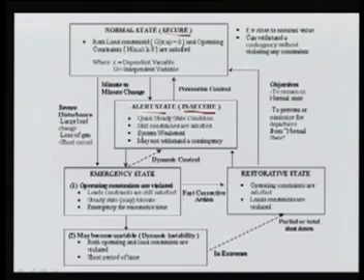So in the normal state, which is known as the secure state, both the load constraints, as I said, and the operating constraints are satisfied, where x are the dependent variables and u are the independent variables. In this state your voltage and frequency vary close to the nominal value and it can withstand a contingency without violating any constraints, then it is known as the secure state.